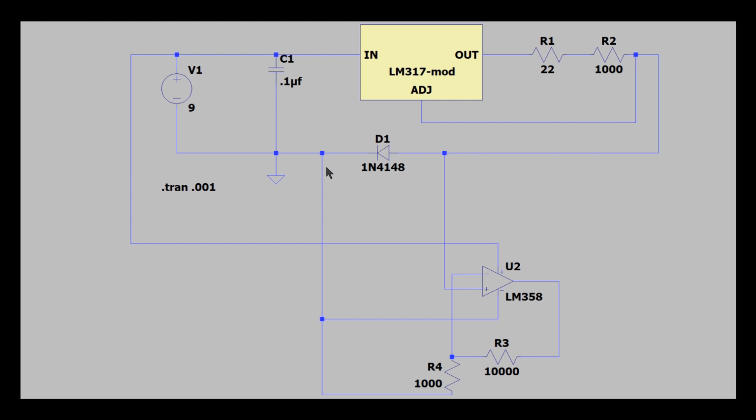So it comes out, and then we put a diode across here to test. This is our DUT, or device under test. And over here what we have is just a little bit of filtering, not really that necessary on a battery, but I like to play it safe to keep oscillations from happening in your voltage regulators. A 9-volt battery will supply this device. It'll be a self-contained device.